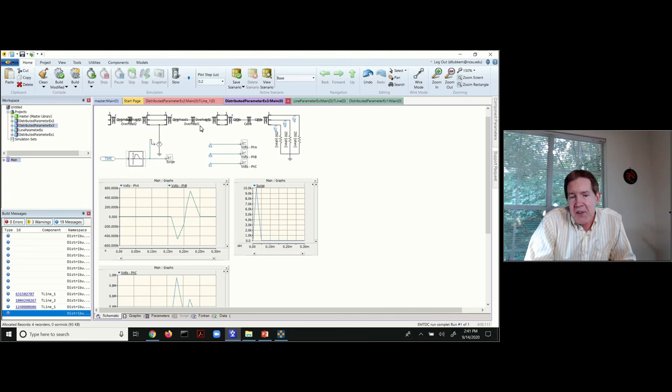When we have the overhead lines and we have this really high voltage on here, as we'll talk about later when we talk about insulation, that could actually flash over, and all we need to do is just clear that fault that's caused by the flashover. But if a large surge hits the cable, then that'll cause a failure of the insulation, which is going to become a permanent failure. So we'll get into that later on, but these are some preliminary things you need to have in order to do lightning strike analysis and then later on to look at insulation coordination.